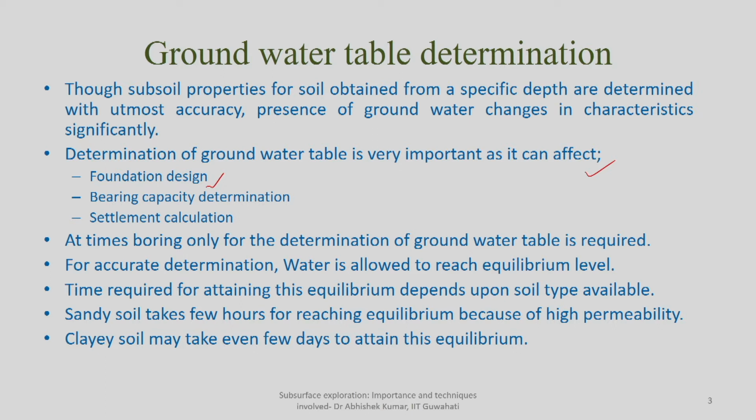So, in the present condition, considering only the soil type, if we are proposing a shallow foundation, whether that shallow foundation decision will remain sustainable after accounting for a shallow groundwater table can change with the condition of the groundwater table, because the groundwater and its effect on the soil available in the zone of influence will finally control the behavior of the foundation. So, that is why the presence of groundwater or the groundwater table also determines what the foundation design will be.